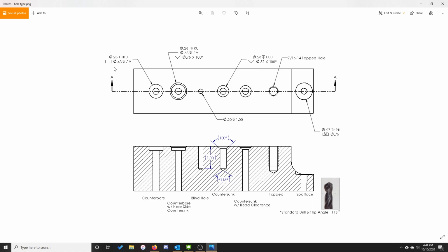The upside down staple shape tells us that the hole is going to be counterbored, with the diameter and depth for that option displayed next to it. The stretched out V shape means that it's countersunk, and it gives us the given diameter and the angle that we can set into the relevant input boxes back on the Hole Wizard.